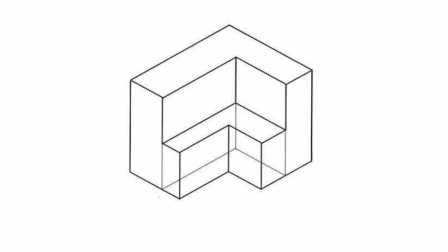And just like that, by combining the shape information from the top view with the height information from the front view, we've successfully translated our 2D drawings into a complete 3D object. We've proven that these two views work together perfectly to define every part of the geometry. So, we've seen how a one-view drawing is the express lane, and a two-view is the smart, efficient route. Mastering when and how to use them is a true hallmark of a skilled drafter.